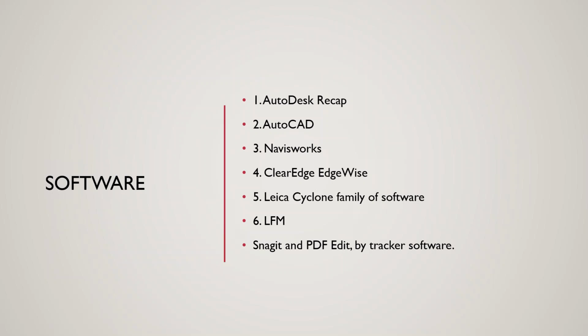ClearEdge Edgewise is probably my favorite tool, a middle tool. Then Leica software, a family of software, Cyclone. That is a set of tools that work very well. There's a lot more investment. That investment may go anywhere from $50,000 to $100,000 to get the whole suite of tools. That's one of the reasons for people starting out, I recommend going towards Autodesk Recap and AutoCAD, because most people already have those tools.